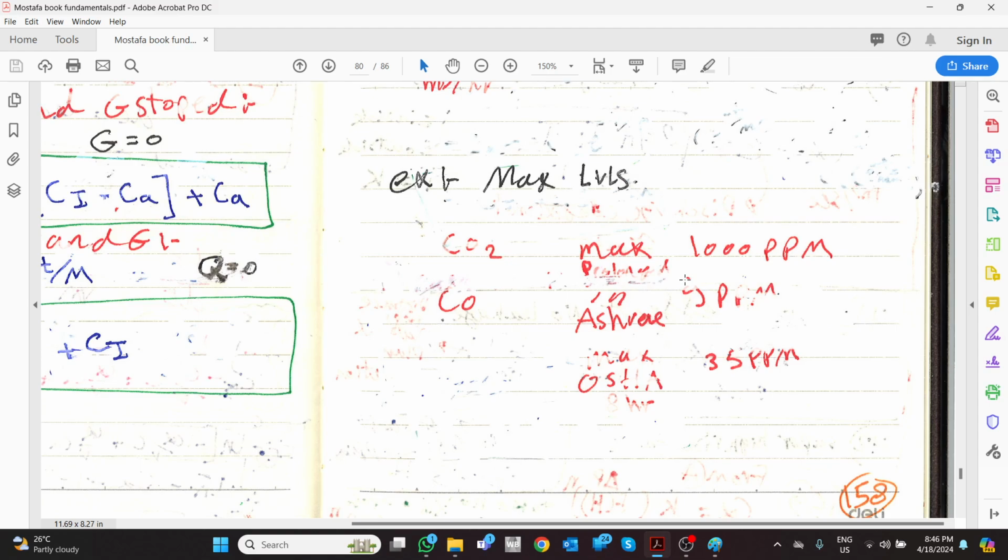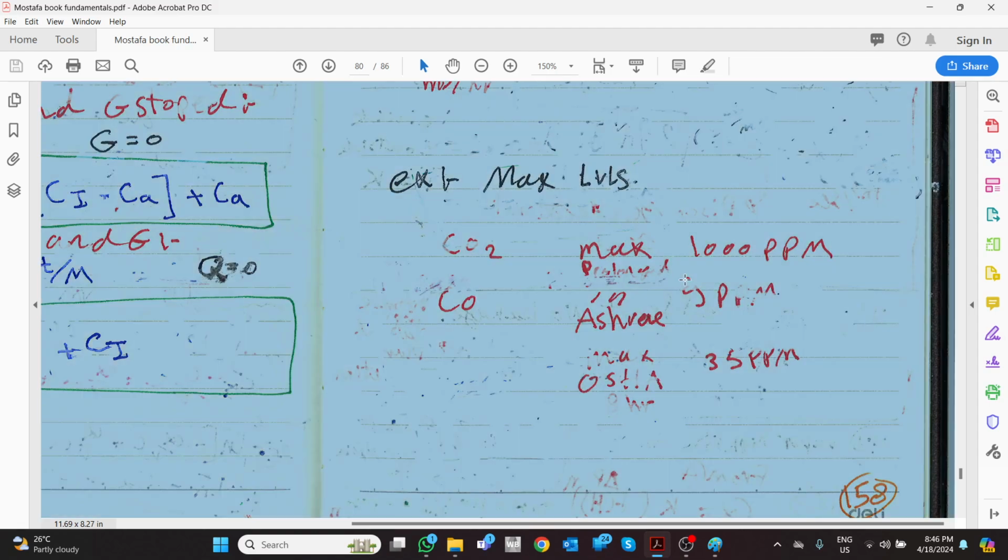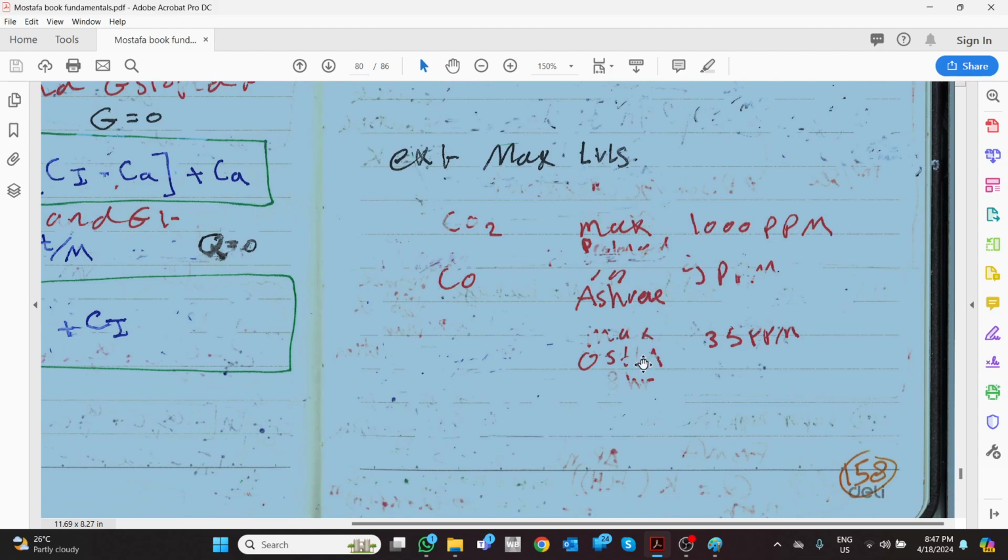That is why in the car park we define the CO sensor based on 2 levels: one is the maximum as per ASHRAE or whatever, and one is lethal, where you need to run the fans at full speed. Some consultants do it 10, 30. It is okay.